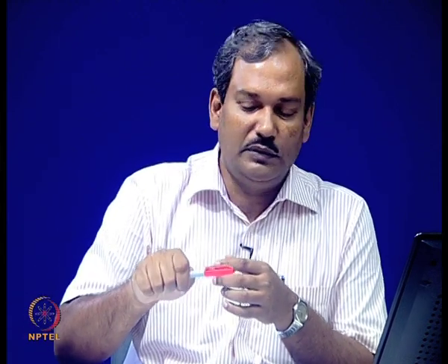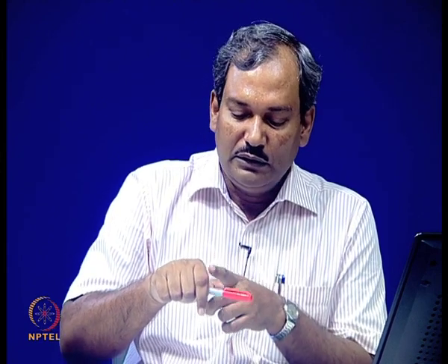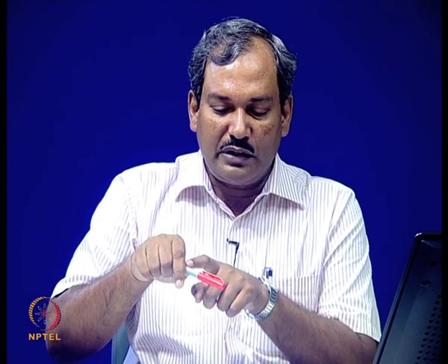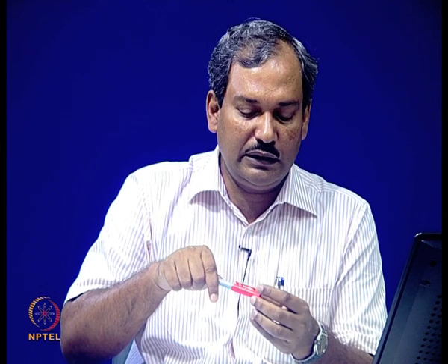Where you are touching the scoop, that is your evaporator, your heat source. The liquid will evaporate, whatever liquid you choose; you have to choose the liquid in that way. The vapor will travel through the scoop, which will have wicking material inside it. It will come over here and condense, in contact with the ice cream, and release the latent heat, and that will locally melt the ice cream, and you would be able to scoop it out. So, an example of a heat pipe.